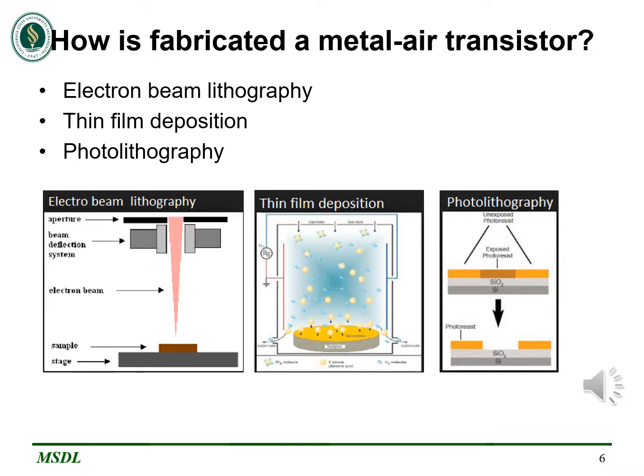In this project, a gate oxide thickness of 50 nanometers was utilized for gold and platinum devices. It was increased to 300 nanometers for tungsten to provide improved tolerance to the gate insulation. High-resolution electron beam resist, polymethyl methacrylate, was spin-coated on the pre-cleaned substrate. Spin coating was a two-step process to achieve a bilayer resist. Copolymer EL3 was spin-coated and soft-baked at 180 degrees Celsius for 5 minutes. Then PMMA A2 was spin-coated followed by identical soft baking. The resulting thickness of the bilayer resist was 120 nanometers.